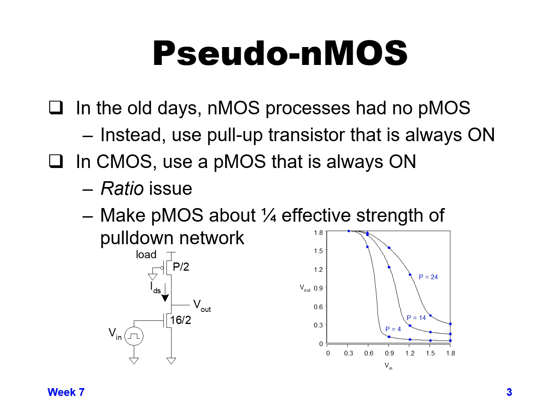If we make our PMOS device too strong relative to the NMOS device, if we look at the chart on the lower right, let's say we make P a size 4, so we have 4 over 2, which is the size of the PMOS device, so a size 2, and the NMOS is size 16 over 2, so size 8.